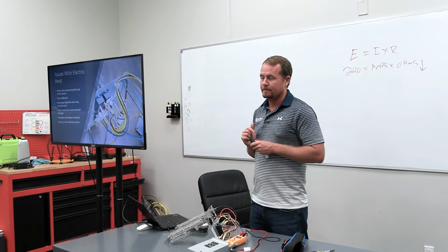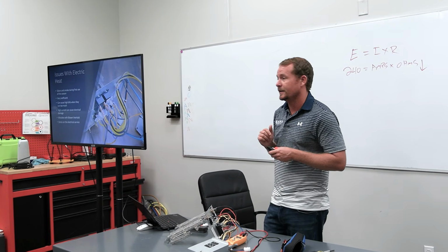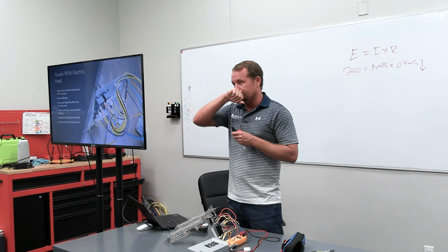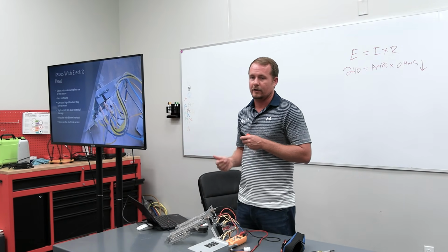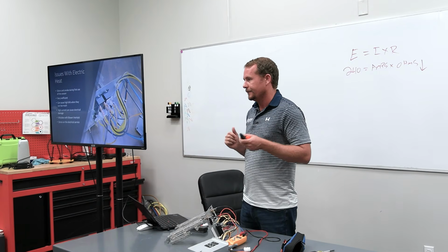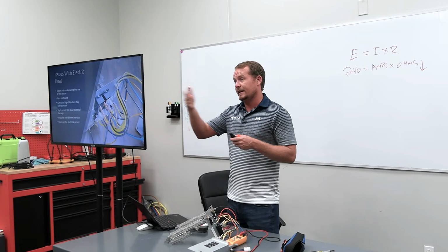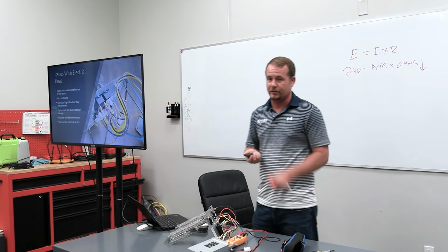The Ecobee is like the easiest for that, the test equipment. Exactly. Also Carrier Infinity, same thing. If you go up and you're doing a maintenance or a service on a Carrier Infinity system, just go into the installer setup and set it into the mode you want it to run in. And then that way you can actually test all the different modes very easily, because you actually get a readout too of a lot of your key readings right from the control.